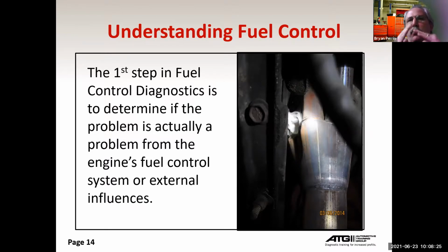When something like that happens, a lot of times you lay the bead across the crack, and then you lay another one over and then over top, and you bridge it out farther, because the metal right next to the crack is the metal that's weak. By spreading it out through a couple of passes, I can spread that stress out and also the heat dissipation over a bigger area, which normally keeps it from cracking again.